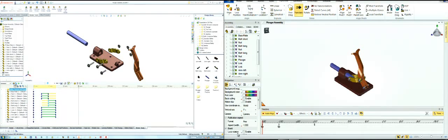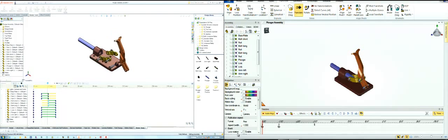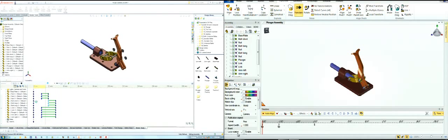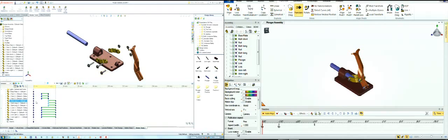Now, if you were to play that from the beginning, oops, yeah, it didn't move. It didn't do what I said. Why didn't it do that? Because I didn't tell it to recalculate. And you saw those yellow bars there? They were all left over from last time. A lot of people get in trouble because they forget to calculate.